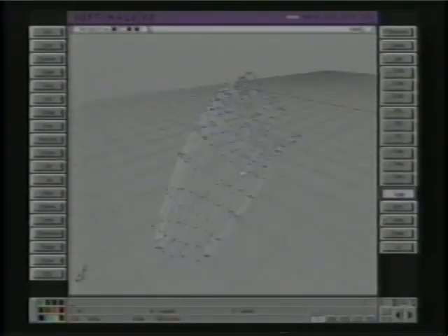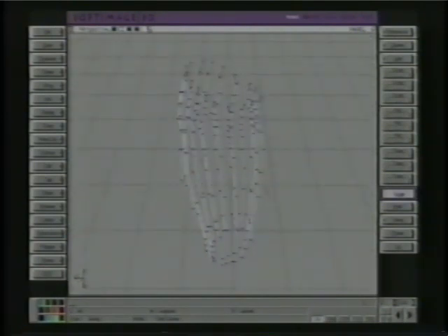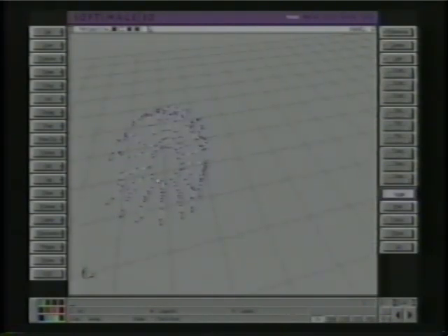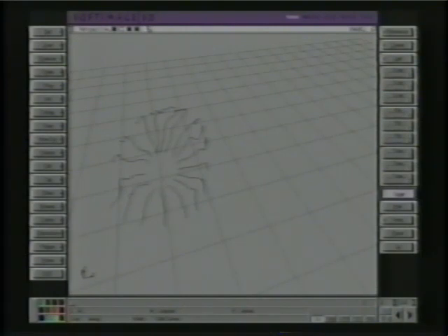Now I'll get back to skinning Stewart's arm here. If you have lines that are going this way, what you want to do in a skinning operation is make sure that you'll be able to see all the curves as you're doing it. So if it's arranged like this, you want to make sure that you're maybe looking down it, or you have multiple windows open, you can look that way.